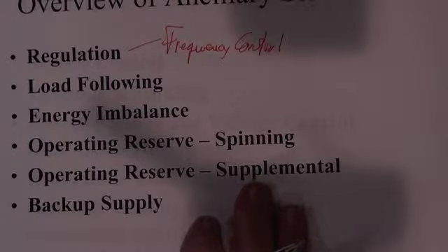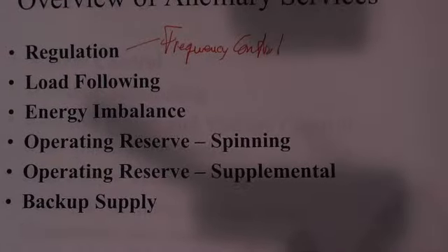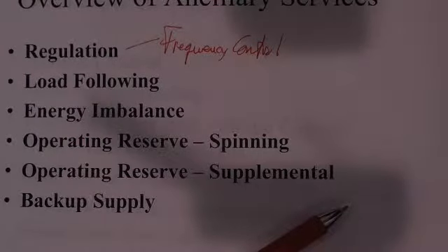We've dealt with that. So what we're saying is, if you're going to be an independent generator and you are going to connect up to the power system, we're going to require that you become part of the frequency control system. You have to have governors on your generators. You have to have control systems so that we can change your set point up and down in response to load controls or in response to loss of generation when the frequency goes down real fast. That's regulation. You're going to be part of the frequency control, and you say, but wait a minute.